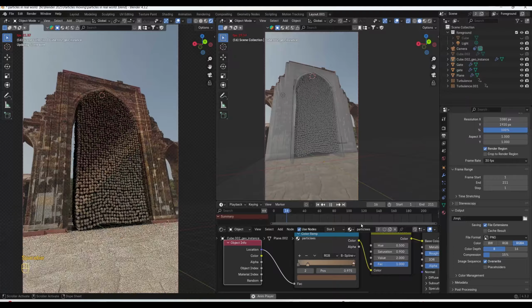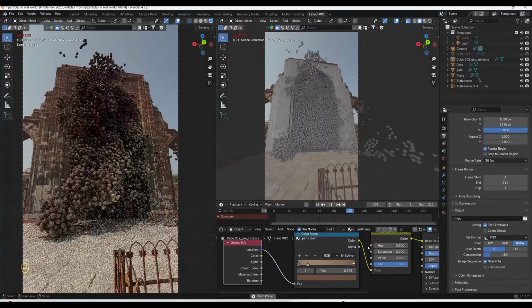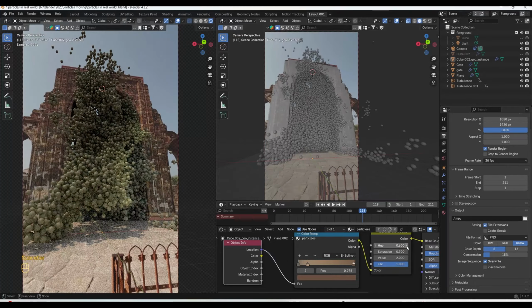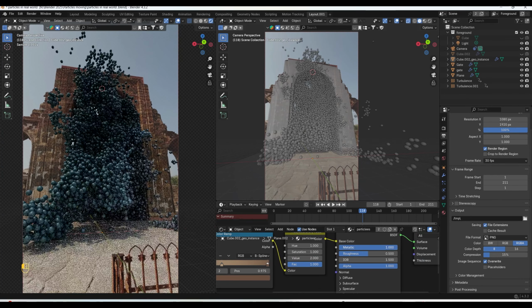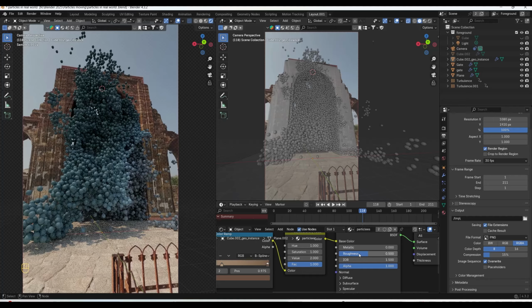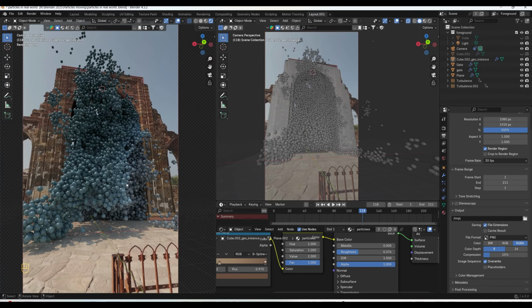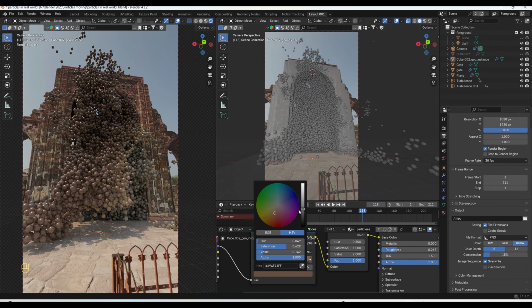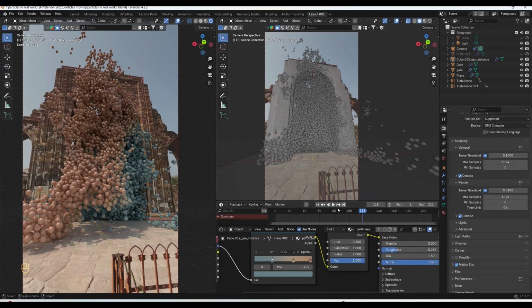So we have a lot of options to play with and check what's working and what's looking good. In the hue you can play, and here you can see. After this I can also make this metallic, or I can play with the roughness. So I will make the roughness down, and in the coat I can make it high and make the roughness a bit, kind of reflecting balls. Here I can definitely play and change the colors, and I can also enable the denoiser.